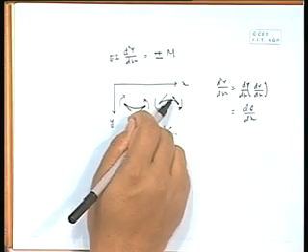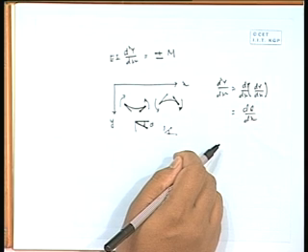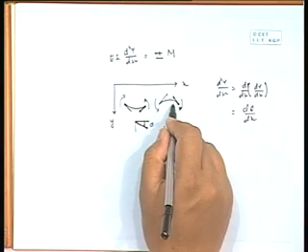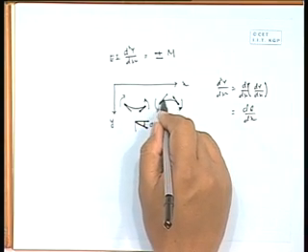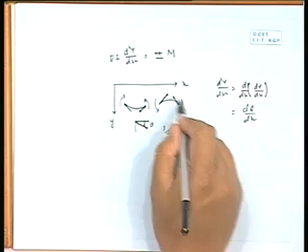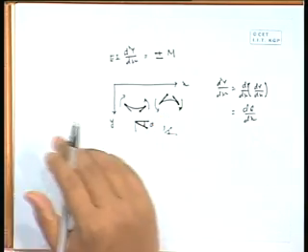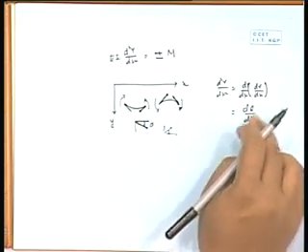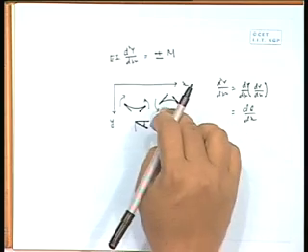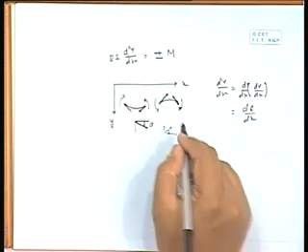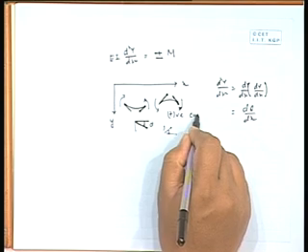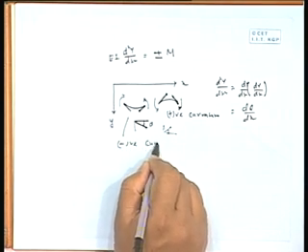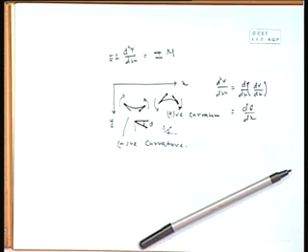So, positive slope means with increase of x, the value is increasing in the positive direction of y, and here if you increase x, y is decreasing. Okay. So, this is a negative slope, that is a positive slope. So, rate of change of slope, this minus this divided by length dx, that will be basically d theta by dx or d2y by dx square. So, this will be a positive curvature, and this should be a negative curvature, right.